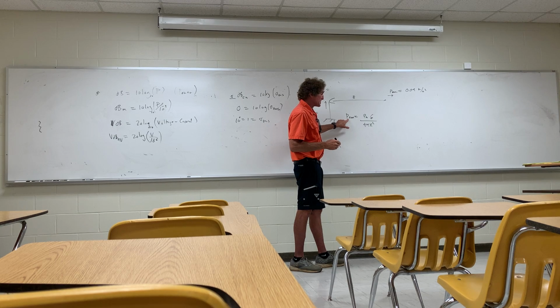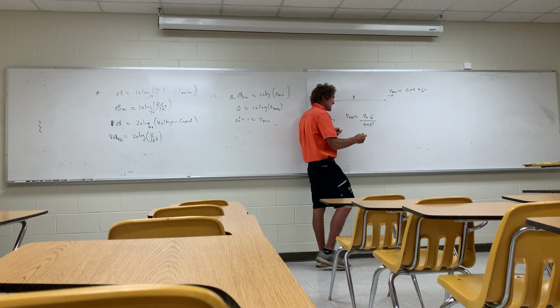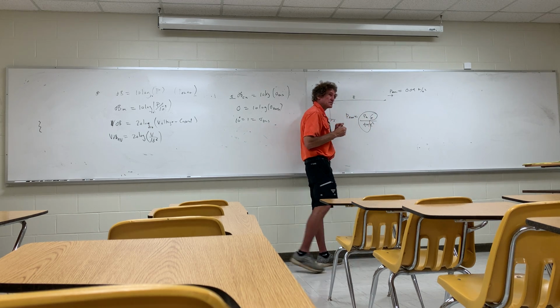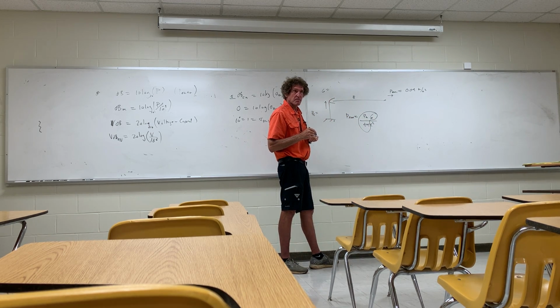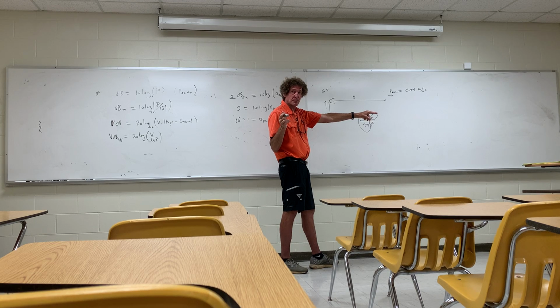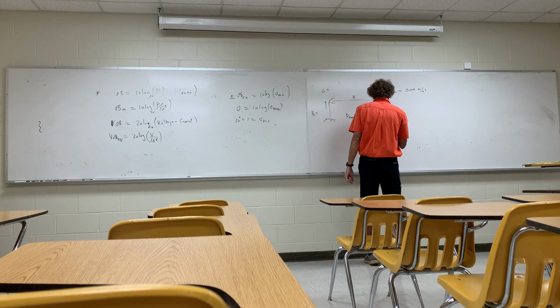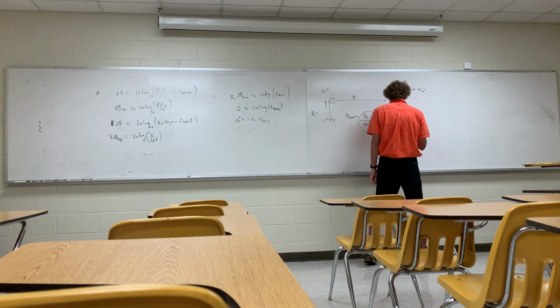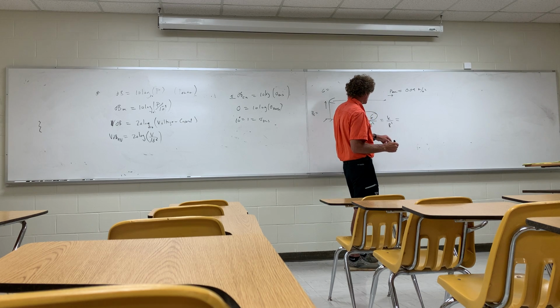So what they give you is this, and if you look at this for a second, all this stuff is one big constant. Do you all see that? It doesn't change no matter how far away you go, as long as you don't move your azimuth or elevation angle. So I can just put it as one constant, K, over R squared. Now, in our case, we know what it is at a certain range.